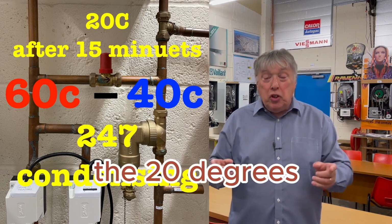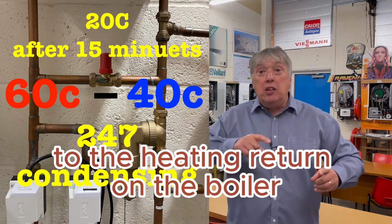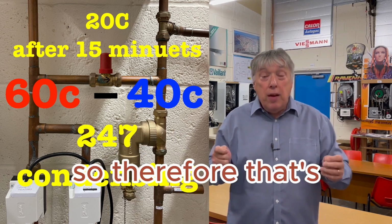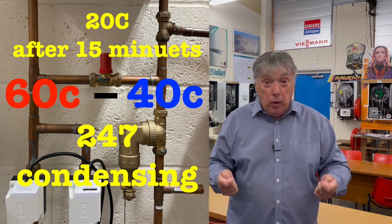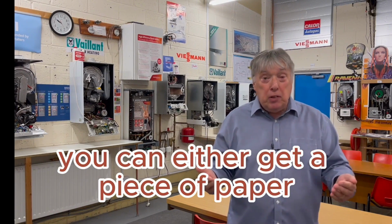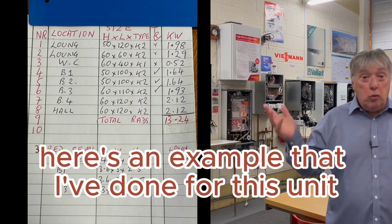The 20 degrees we calculate from the heating flow to the heating return on the boiler, and there has to be a 20-degree rise or difference. So therefore, we move that over to the heat loss calculator. Now, there's two ways we can do this. You can either get a piece of paper. Here's an example that I've done for this unit.